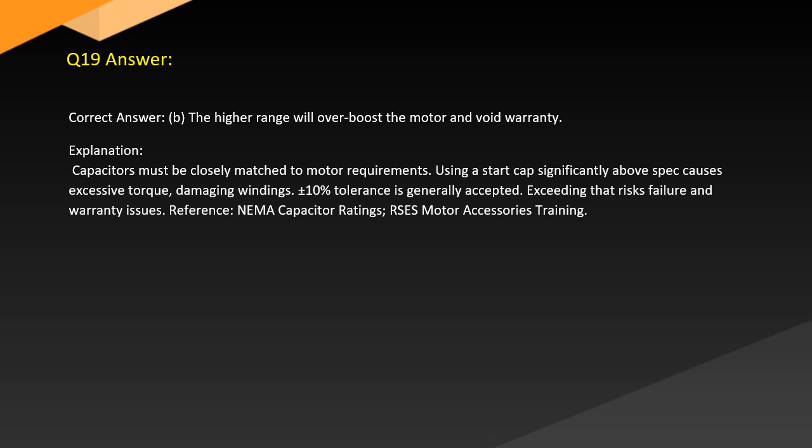Answer. Correct answer: B. The higher range will overboost the motor and void warranty. Explanation: capacitors must be closely matched to motor requirements. Using a start cap significantly above spec causes excessive torque, damaging windings. Plus or minus 10% tolerance is generally accepted. Exceeding that risks failure and warranty issues. Reference: NEMA capacitor ratings, motor accessories training.